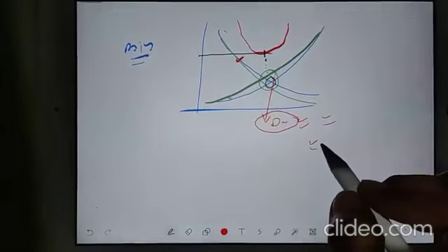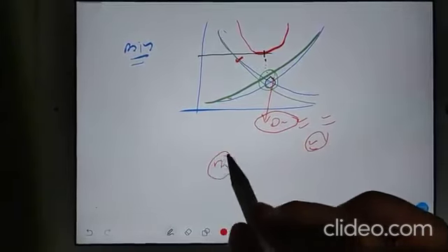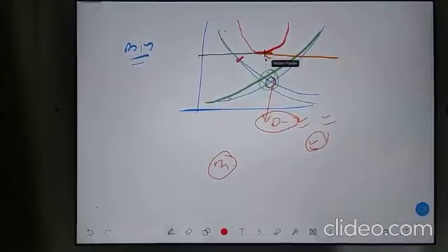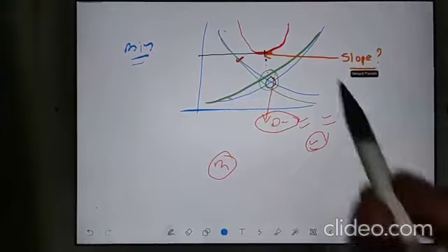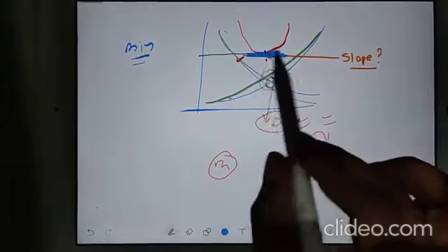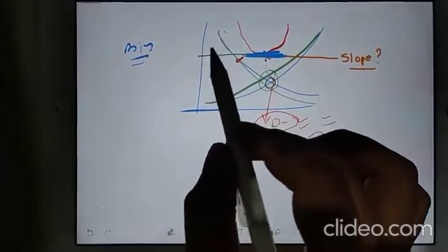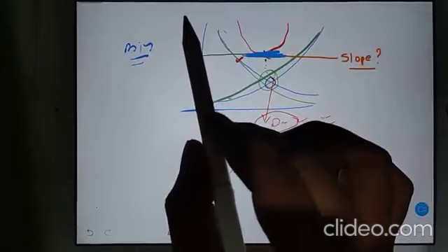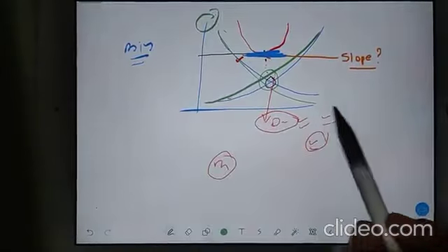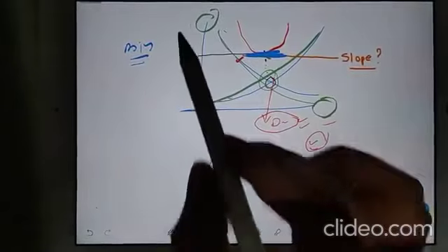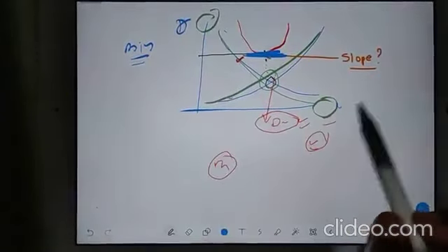In the same way there is something called minimum power condition. So what about minimum power condition? What will be equal when we are talking about minimum power condition? When you deal with minimum power condition, you will say the slope is zero, of course. So which slope are you talking about? In which two axes is this graph drawn? This graph is drawn between drag and velocity.